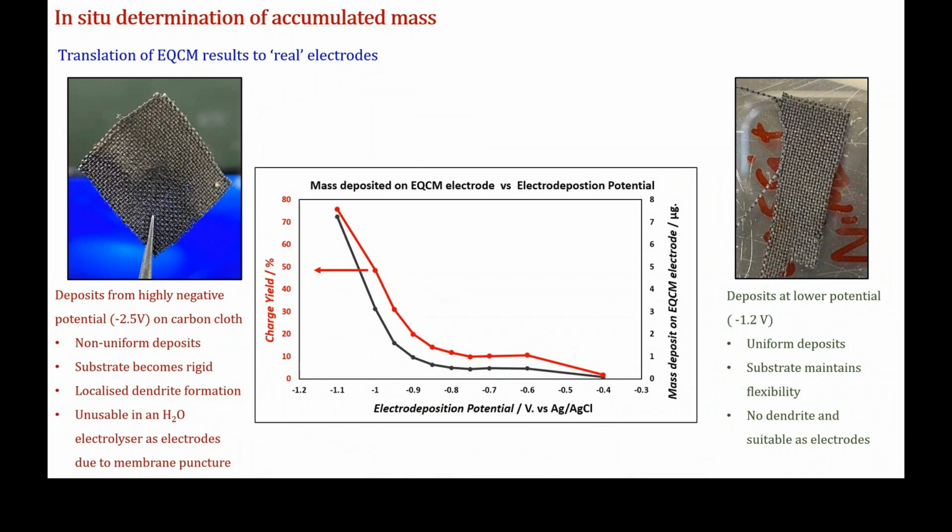And when you look at the results from the electrochemical quartz crystal microbalance, you can see that you're just applying way too much overpotential. The nickel deposition is probably all finished, and you're starting to get more hydrogen evolution, which is ruining everything. And then when the conditions became a little bit more appropriate, based on the results that were obtained with a crystal microbalance, the deposit was much better.